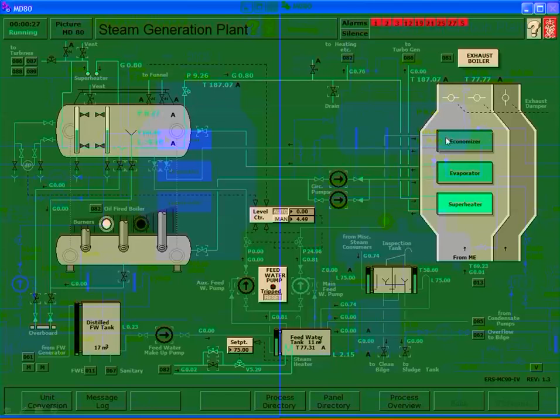Now, if you were going to natural gas, a clean fuel with no sulfur, or LNG, we wouldn't do this. We'd want the economizer to pick up absolutely as much heat as we could, and we would drop the flue gas down as low as we could. We want that heat. The problem with heavy fuel oil, a high sulfur fuel, is that we can't, because the acid is so detrimental.